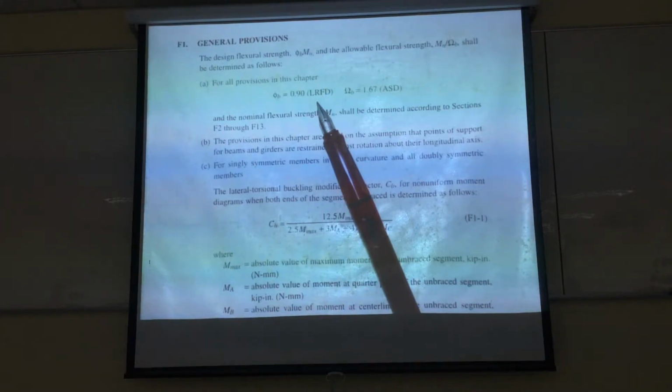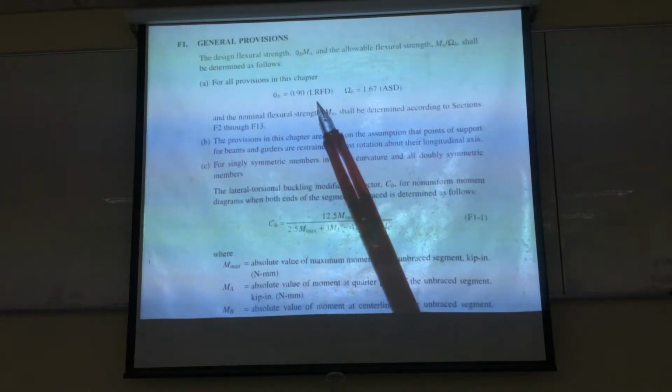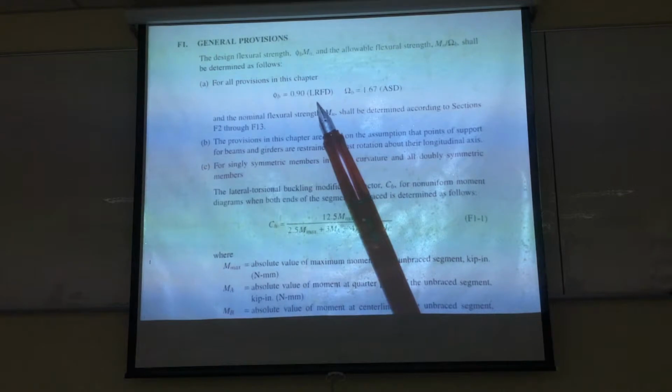For example, you talk about warehouse load. Warehouse load could vary from 500 kilograms to 10 tons per square meter. In the recommendation, sometimes you find 500 kilograms for warehouse load, but generally it stacks up. When it stacks up a lot, you can get up to 3 tons, 5 tons.